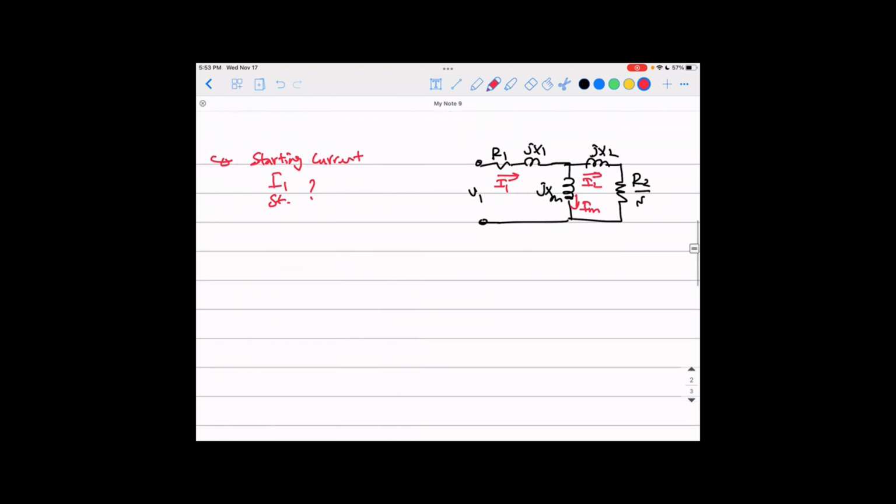We said before that the machine's current I1 will equal V1 minus E, the induced voltage, divided by some sort of impedance. I'm not talking here about a specific impedance of the stator or the rotor, but it's a very general equation for any kind of machine, because you're talking about just a coil, the stator coil, with the current moving inside it.